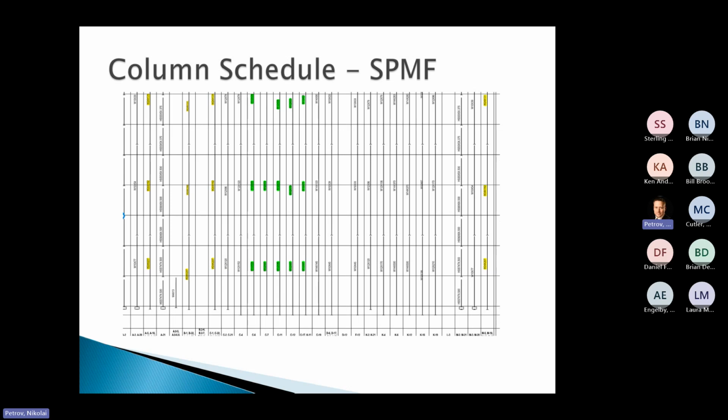Because when we went from brace frames to moment frames and took things out of the core, we didn't have to have all these columns to complete the brace frame where, okay, the brace frame could be here, but it has to stop here because we have a hallway, or we have a duct chase, or we have an elevator or something else. So we actually were able to completely eliminate, I think, 5 columns from the center of the building.